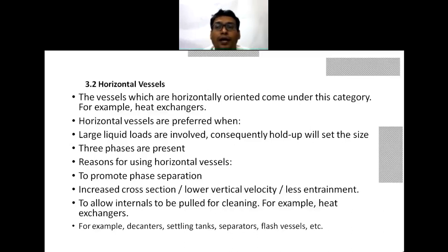If I'm handling a large quantity and I increase the height, the volume will be the same for any tank, but the head will be more. The liquid head will be more if I'm using a vertical tank, so the static pressure head will be more.